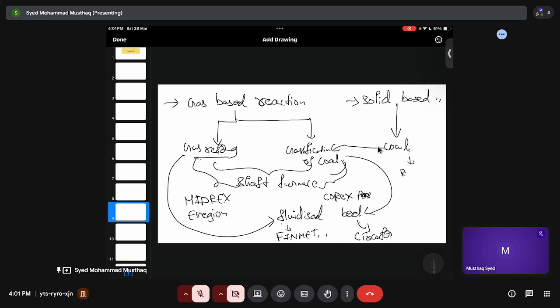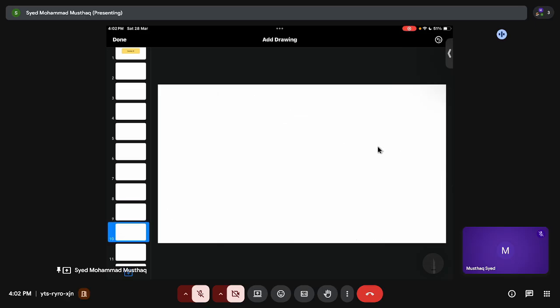And if I use a rotary kiln, again please remember the difference between the rotary kiln and rotary hearth. A rotary kiln is a horizontal tubular furnace, but it is in an inclined position. It will look like this. We have seen this actually, and this is called the SL/RN process. Okay. And the rotary kiln will mostly look like this. You charge at one point, you take it out from the other point, and this guy will turn. It rotates at a certain RPM, not very high speed, but a certain low RPM. Okay.